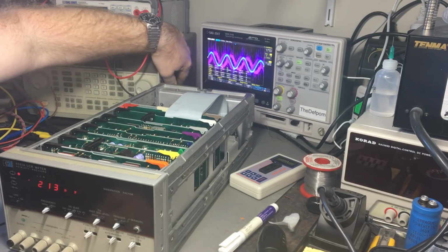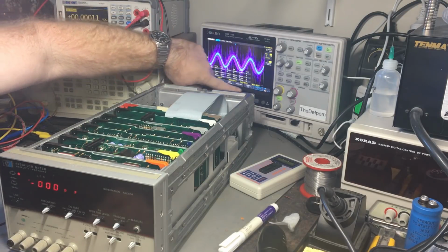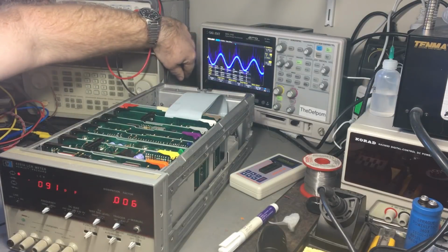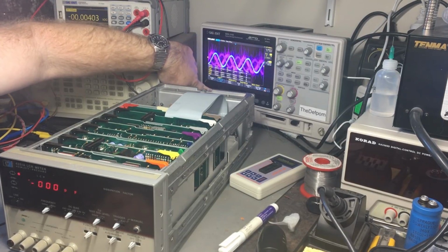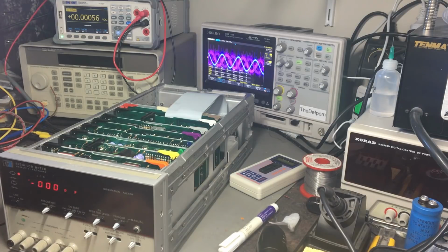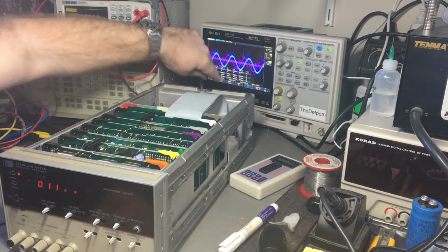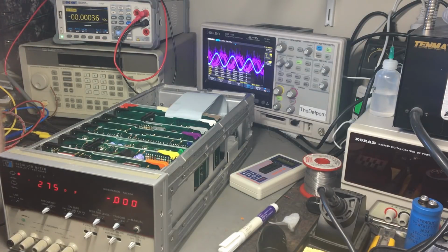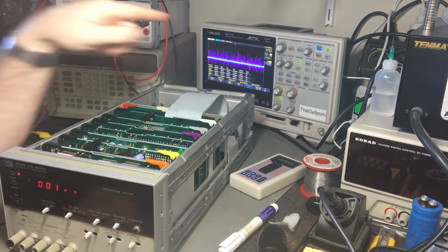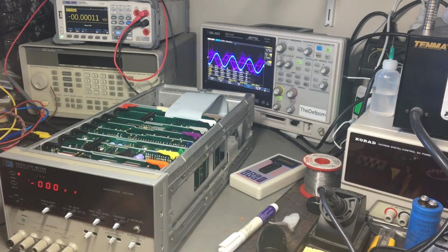Noise rejection on, maybe helps slightly. Bandwidth limit, stick that on 20 megahertz. It helps slightly as well, not a huge amount. 50 ohm, yeah, this kills it. So I'll do that. But I'm measuring 50 kilohertz there, not 120, which is interesting. But see, there's bloody spikes in there, which may be a sign of a problem. I don't know yet.